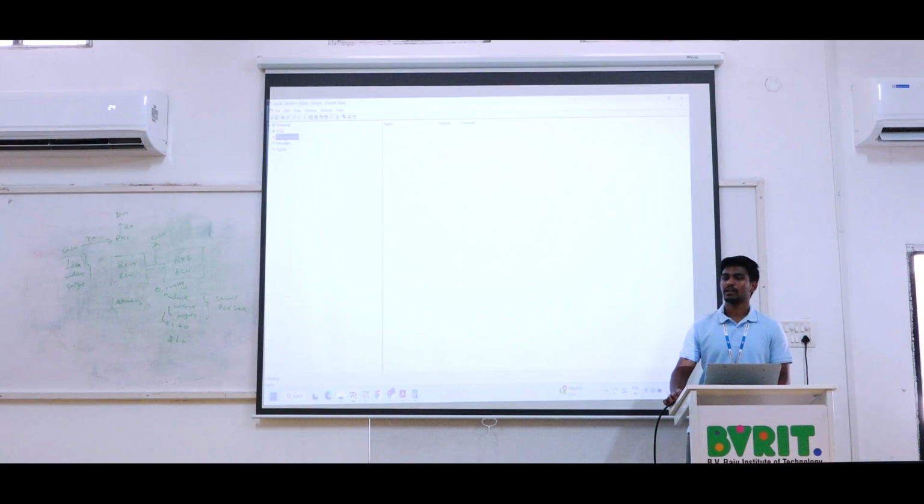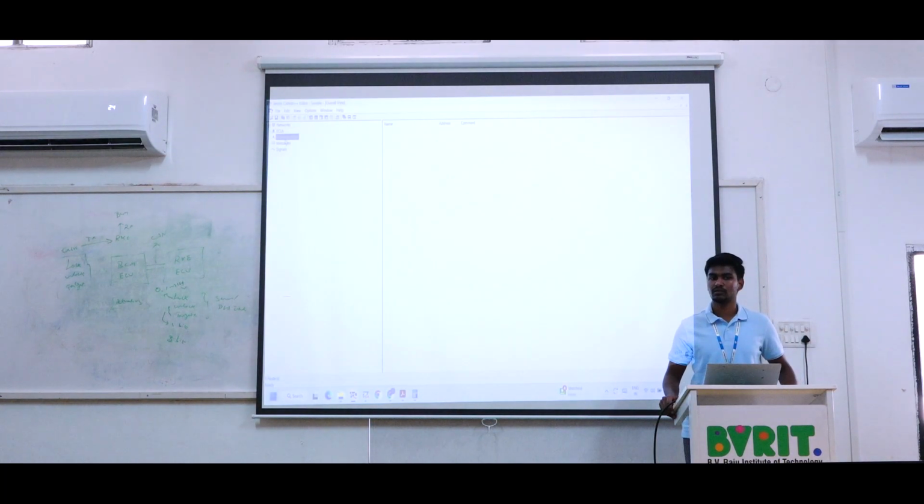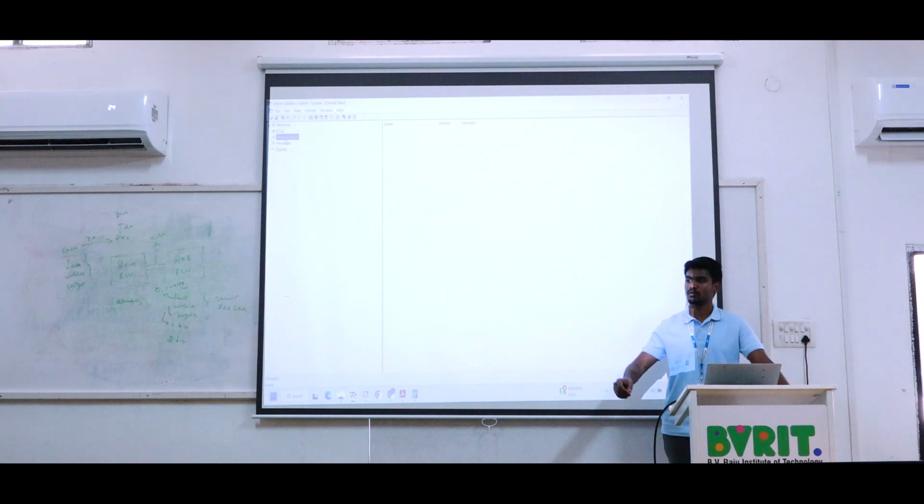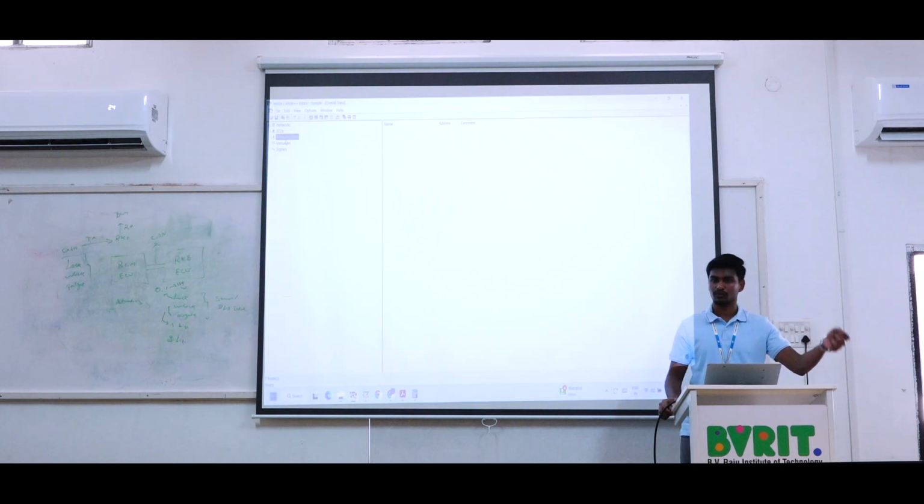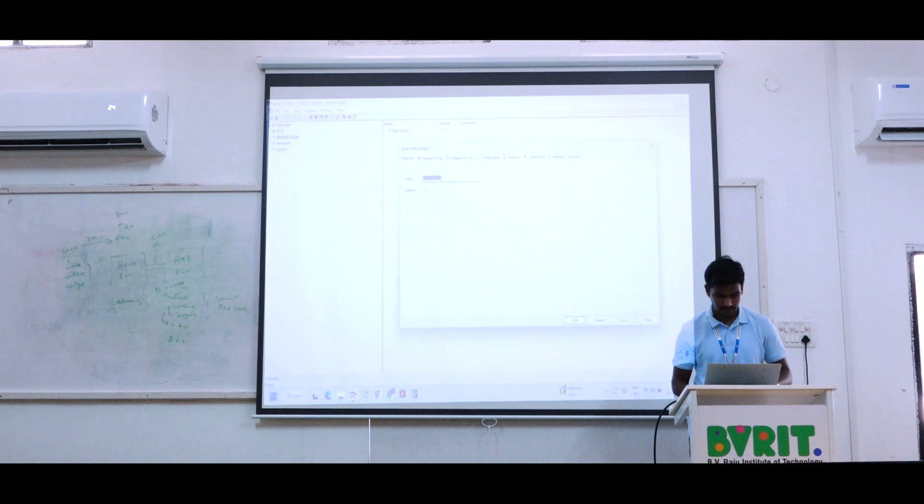As per our requirement, what network nodes do we need? For each, I will provide you one transmitter and one receiver node, or else for one transmitter node I will give you 3, 5 or 6 receiver nodes, because one signal can be received by one or more nodes. For the network nodes, right click. We will get the box New, and then I can name the transmitter RKE ECU. You can just type RKE, that's enough.